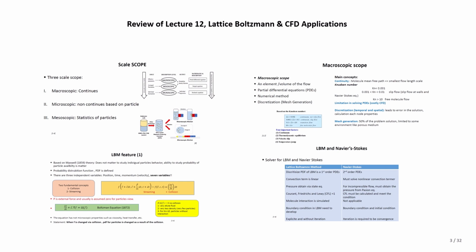We saw some weaknesses of the CFD in contrast to the lattice Boltzmann equation. Additionally, regarding high performance computing and parallel computing, because the lattice Boltzmann equation works based on two events, which include streaming and collision, it's great for parallel computing. And also for some limited applications like porous media, where regular CFD does not work properly.